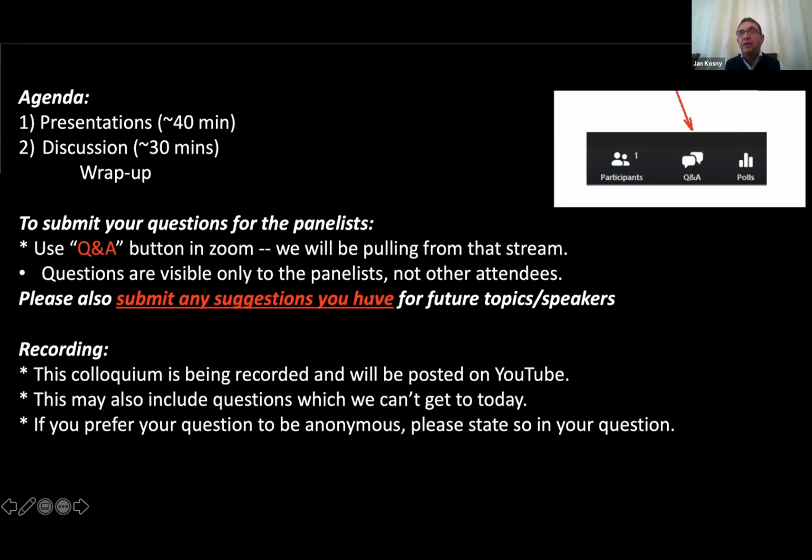We did vacuum insulation on one of the walls in our building, the Fraunhofer building in Boston, on the interior side, which probably all the building science so-called preachers would say is impossible. We did probably a couple hundred different levels of simulation, hygrothermal and thermal.